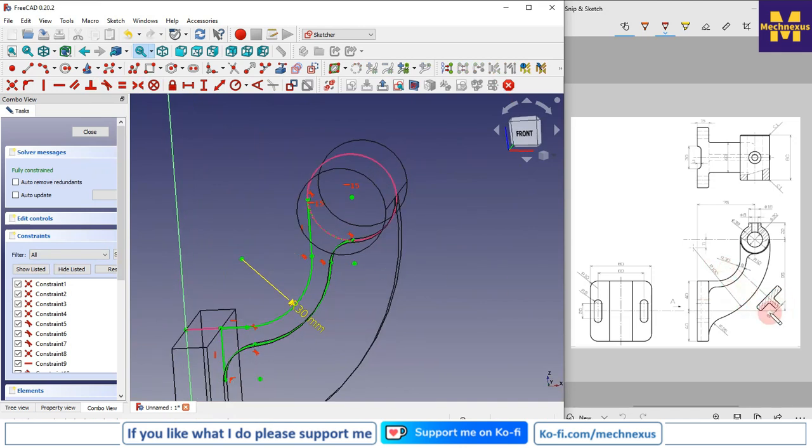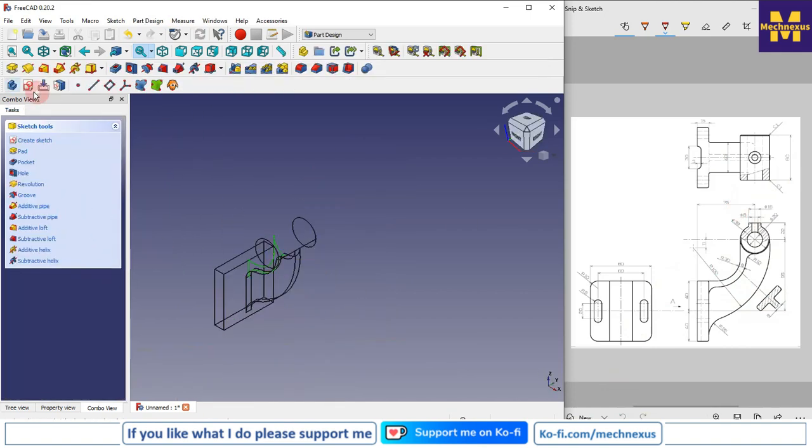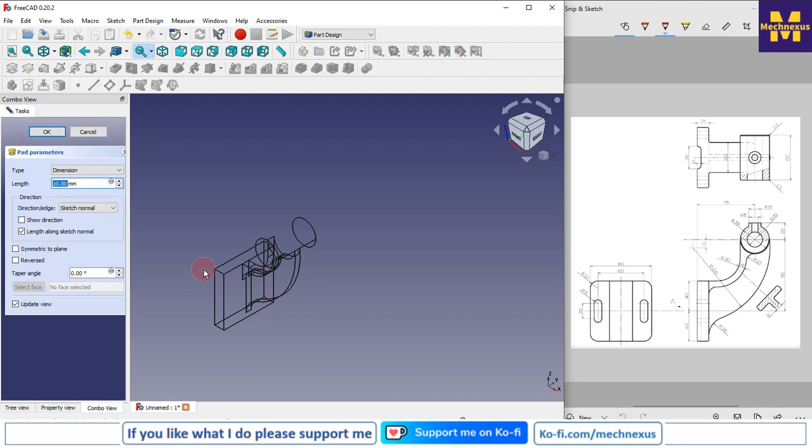Now if we see its extrusion length is 40, so I will close it and click on the pad and switch to the flat lines and give the extrusion length 40, and we will keep it symmetric to the plane.